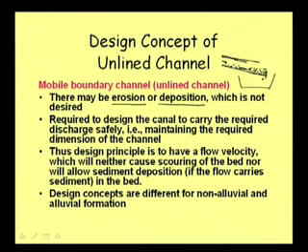Similarly, if it erodes the channel, then also we are not achieving our target. If it is eroding, it will cause damage to the channel. If it is eroding the side, it can get widened. Suppose a channel was like this, and it has eroded this side and bed, then its entire section is changing, and we may not get the required depth that was desired. The flow velocity may again change, and then it may sometimes lead to deposition, initially erosion.